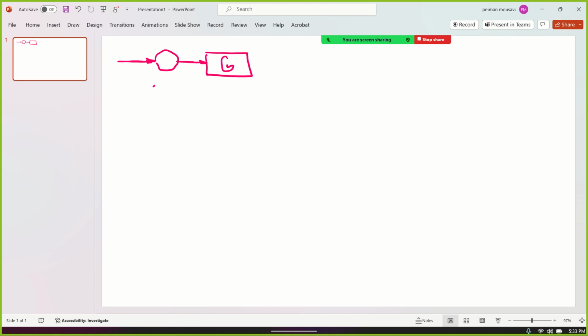Here we had the plant only, not the controller anymore at this stage. And we assume that the sensor is ideal, so there is no sensor transfer function here, that's why it's unity feedback. Desirable input to the system in frequency domain and the real output of the system. And this is the sum operator as I showed you in the Simulink. And we derived together